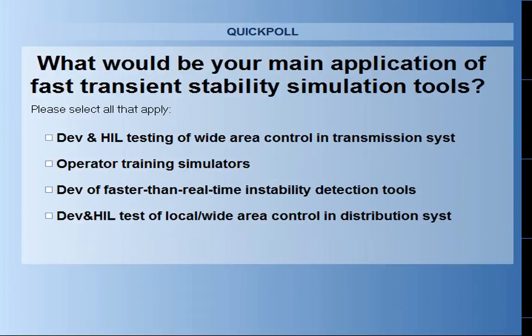To give you an example of the data input, it is a very simple set of tables with well-recognizable parameters for the practitioners of this field. The point being that with ePHASORSIM, once you describe your network and you set up your simulation, ePHASORSIM will allow you to achieve anything you would like to do with transient stability simulation at its heart.